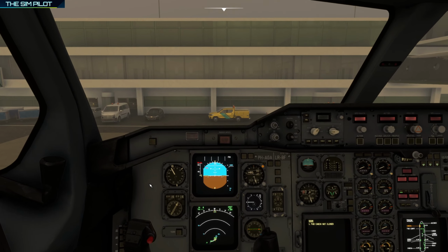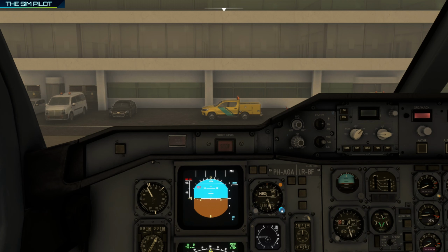They are not set. Let's set our altimeters to 1030. They can be linked in the settings page of the EFB. If you want to link, when you set one, all the other altimeters should be set. The airport elevation should be reading close to 0.